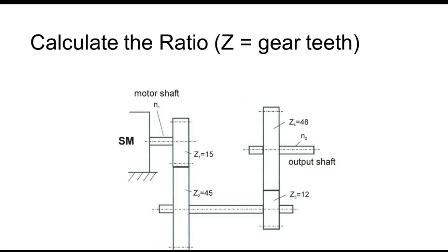So if I've got a little one feeding a big one, which is what we've got here, so what is it multiplied by, so divide speed. You understand that? And then over here on the same shaft, I've got a little one feeding a big one, so this is going to run at a slower speed, but at a higher torque.